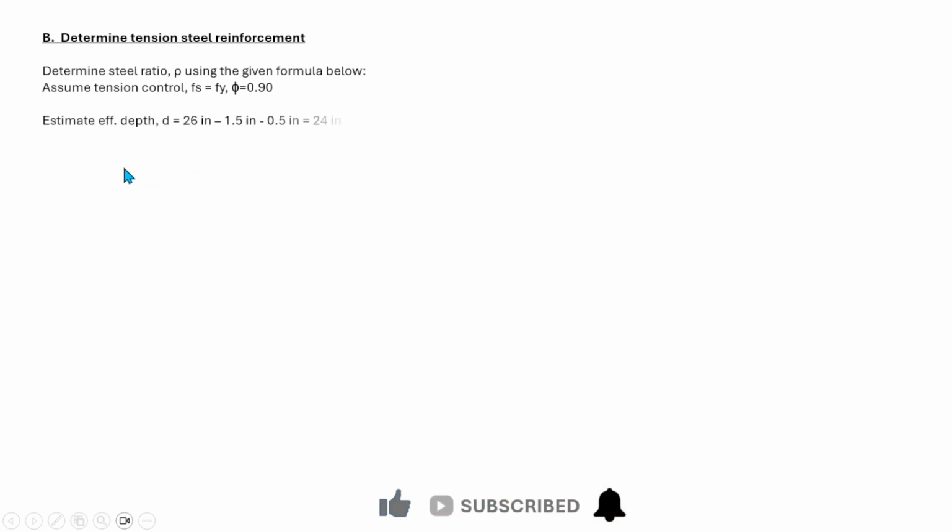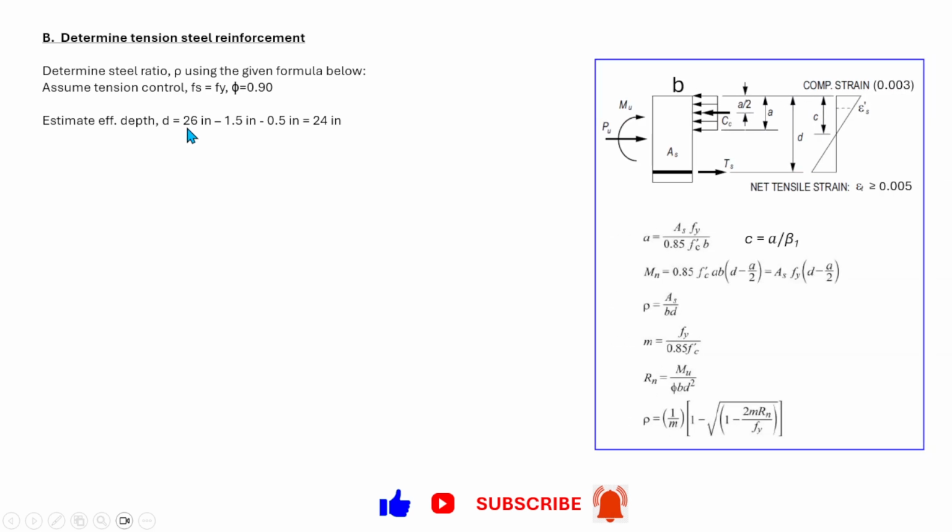Then we can estimate the effective depth of the beam, d equal to 26 minus 1.6 inch for the concrete cover, minus 0.5, assuming that we are going to use 1 inch diameter main reinforcing bars, and that is equal to 24 inch. So by using this flexural formula, we have the parameters m and Rn, so that we can calculate the steel ratio.